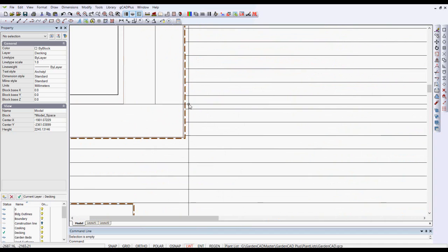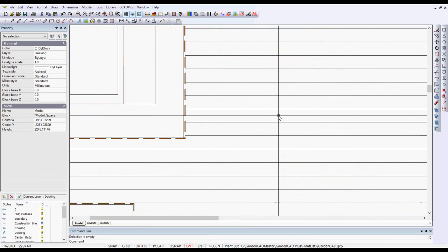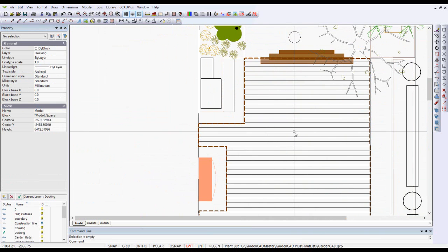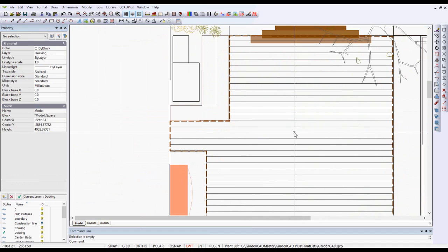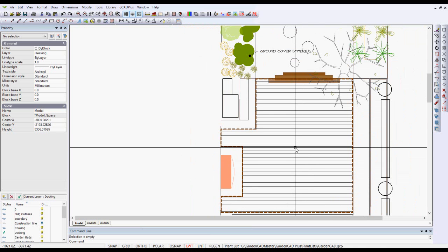If we wanted that to be a much bigger hatch pattern, let's change it to 20, because I still think it's a bit too dense. There, that gives us a different dash spacing. Dash lines are usually used for hidden lines underneath the bearers underneath the deck. Quite possibly here you could even remove that polyline if you wanted to at this stage.